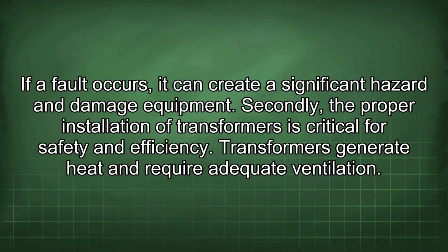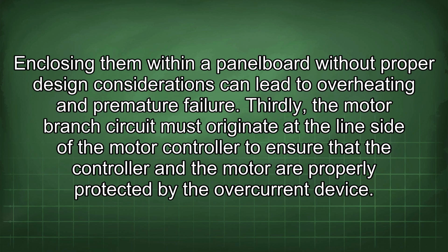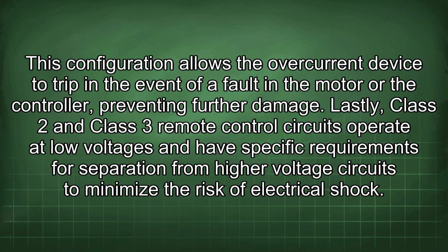Secondly, the proper installation of transformers is critical for safety and efficiency. Transformers generate heat and require adequate ventilation. Enclosing them within a panel board without proper design considerations can lead to overheating and premature failure. Thirdly, the motor branch circuit must originate at the line side of the motor controller to ensure that the controller and the motor are properly protected by the overcurrent device. This configuration allows the overcurrent device to trip in the event of a fault in the motor or the controller,